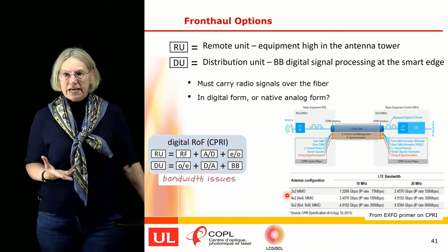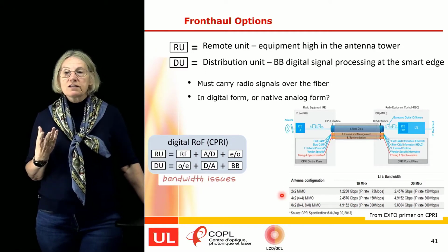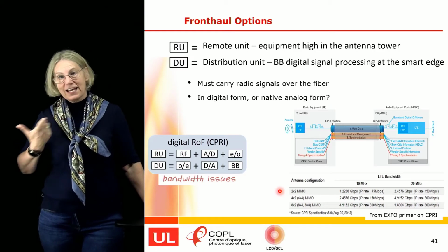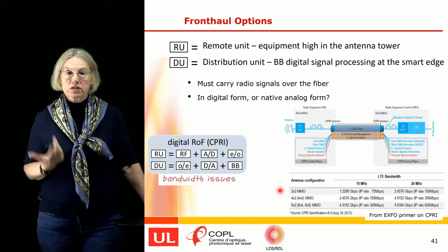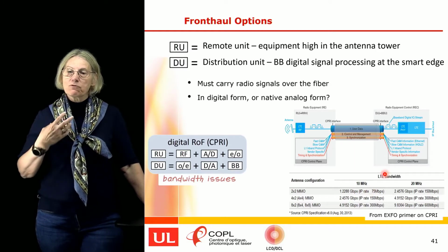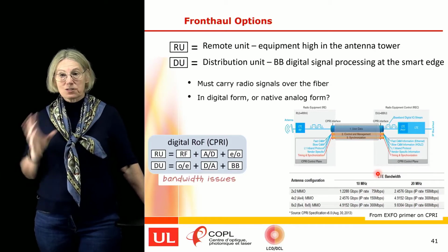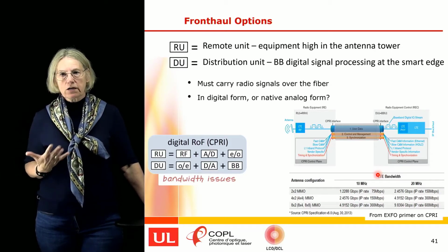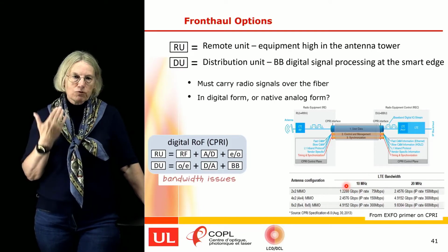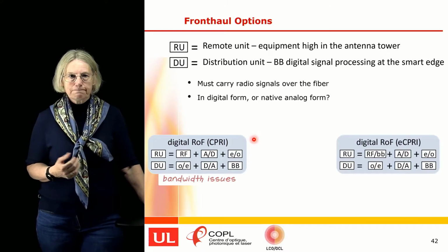So, big expansion, and as I add radio units, I'm getting more sophisticated radio units with more antennas in an array that I'm trying to exploit. Of course, every 10 megahertz channel ends up requiring a different signal for each one of the antennas. And so this bandwidth expansion becomes really critical. And this is what's getting in the way of really exploiting radio access networks which involve fronthaul.